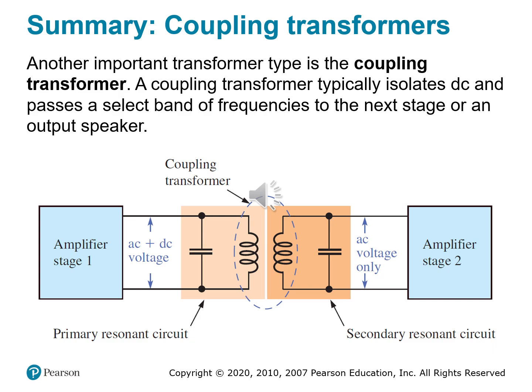You'll find coupling transformers in audio amplifiers, where they isolate noise and preserve tone; radio frequency circuits, where they pass only certain frequencies; and modulation systems, which help transfer power or data without direct electrical contact. The circuit might also include resonant components like capacitors that form bandpass filters that let only a select range of frequencies through. So while isolation transformers keep people safe, coupling transformers keep signals clean, especially when transferring energy between sensitive stages.